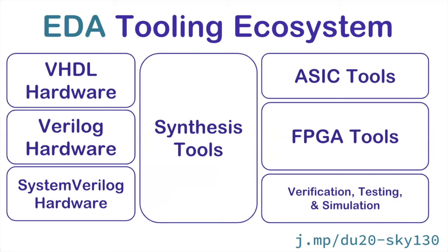In ASIC flow, we have Verilog, VHDL, SystemVerilog as a programming language. And then we use the synthesize tools to synthesize our design to get the netlist. At last, we will use the ASIC tools to implement our design and get the GDS file. The GDS file actually describes the mask in the craft.